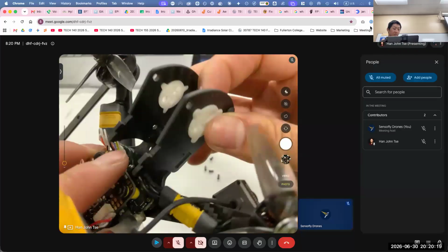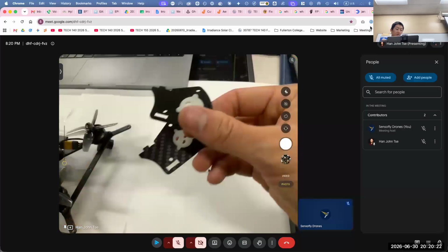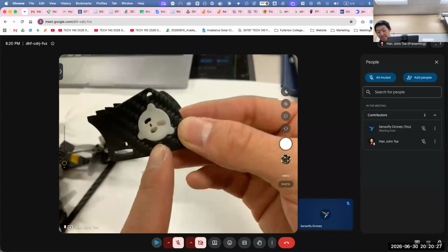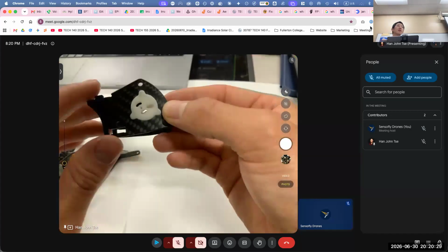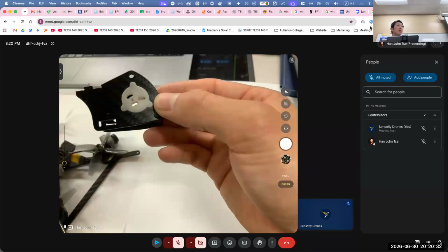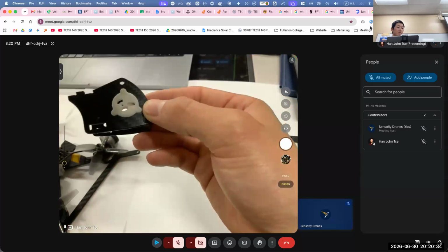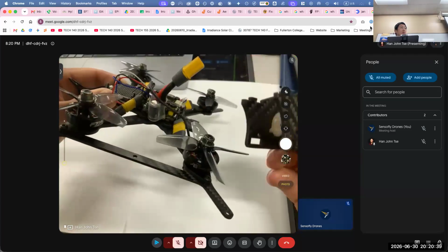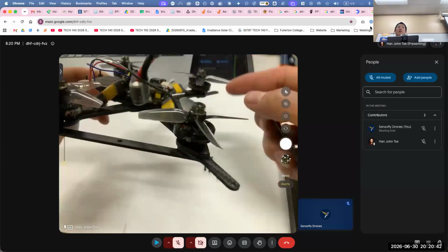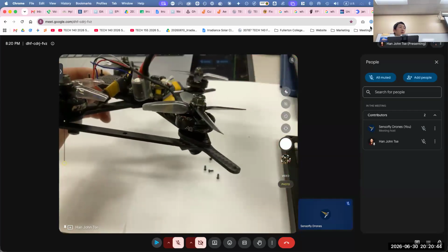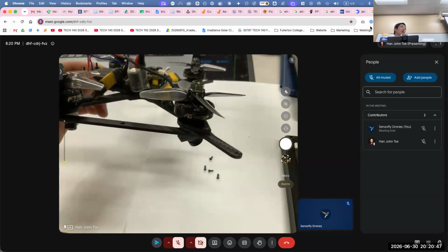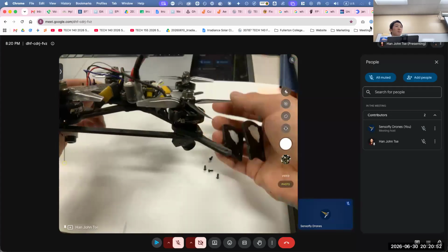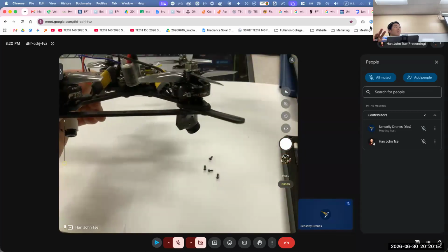What you want to do is have this particular orientation. It's very particular. With our drones, when you're flying them, your drone will naturally pitch down as it's going forward. If your camera is normally pointing forward, it's also going to pitch down, and now you're just looking at the ground. So you want to purposely tilt your camera up a little bit.